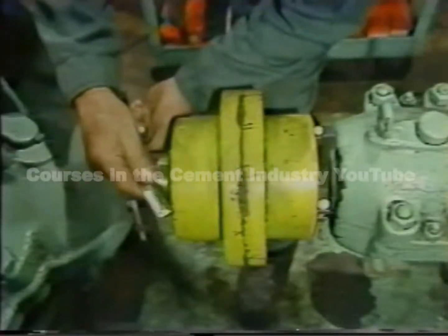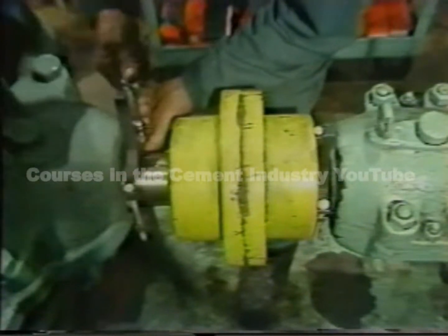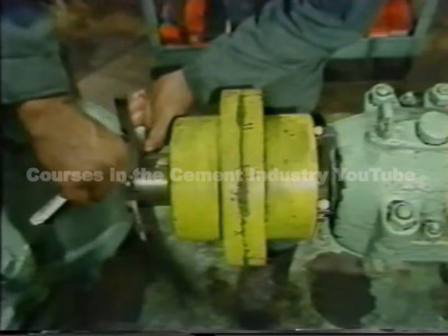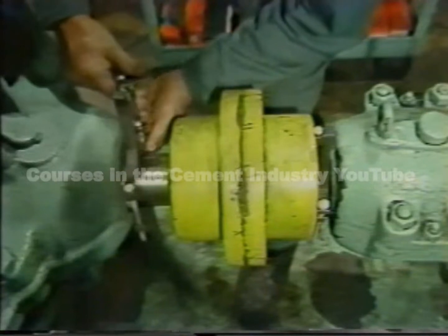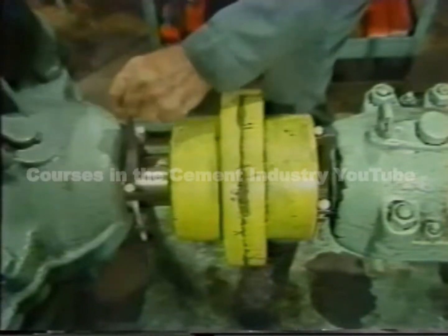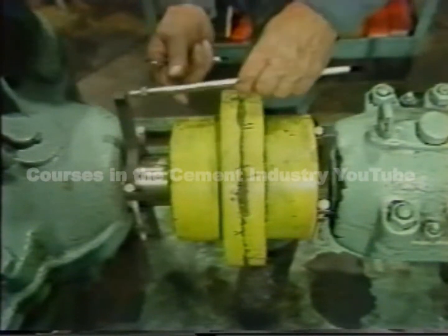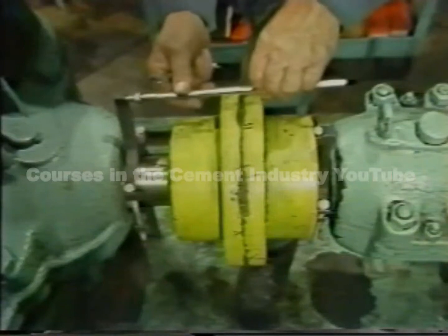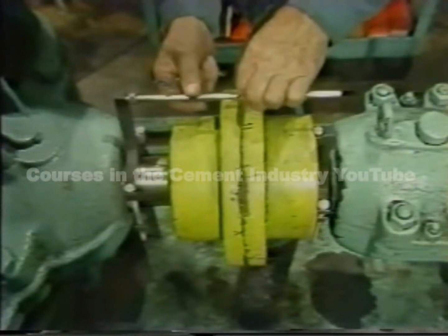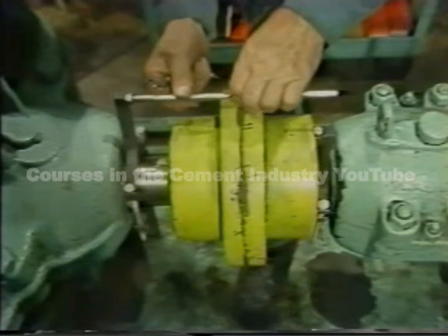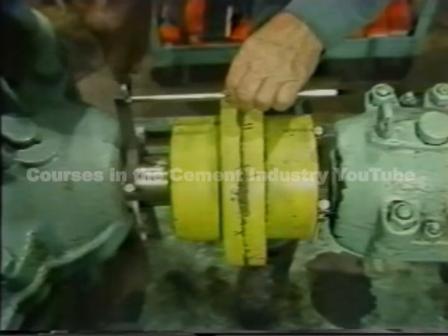After the bracket is up finger tight, a socket wrench and extension can be used to snug it up. Both the bracket on this side and the post on the pump shaft must be rigid. A little shake will tell you whether or not you have a firm mounting. The next piece to go on is the rod that spans the coupling. You'll notice that the post and bracket are offset slightly. That's done in order to give you room to install the dials. The rod must be rigid too.